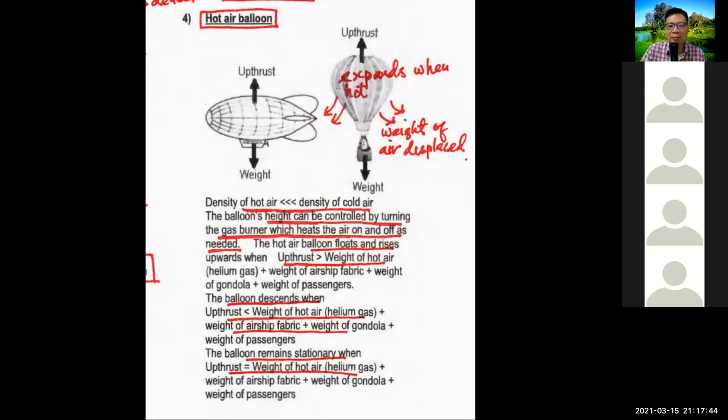Because the density of the seawater depends on the location and the season. Yes, very good, very smart, Kali. The density of the water in the whole world is actually not fixed. From place to place, from country to country, the density can vary. Location, and then for season also, winter and summer, the density is all different. That's why we need the extra precaution, the Plimsoll line is needed. Okay, next question.